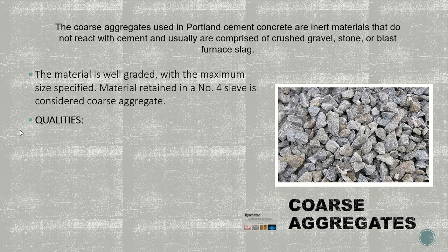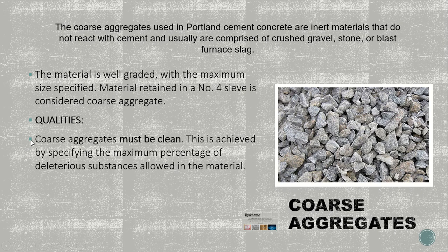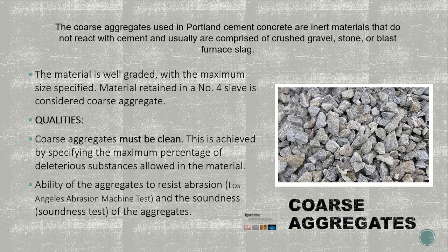The qualities of coarse aggregates. First, coarse aggregates must be clean, which is achieved by specifying the maximum percentage of deleterious substances allowed in the material. Other qualities include the ability of the aggregates to resist abrasion, determined by the Los Angeles abrasion machine test, and the soundness test.